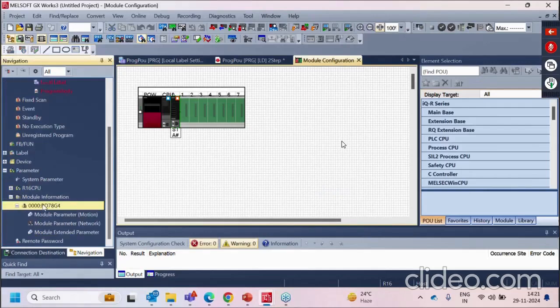Okay, and you can see the starting address of that model. It starts with 0. So whenever we are going to use the motion model, we have to check the starting address also, because as a first priority we have to do the program for the servo on, so the bits required are there. So we have to check the motion model's starting addresses also.